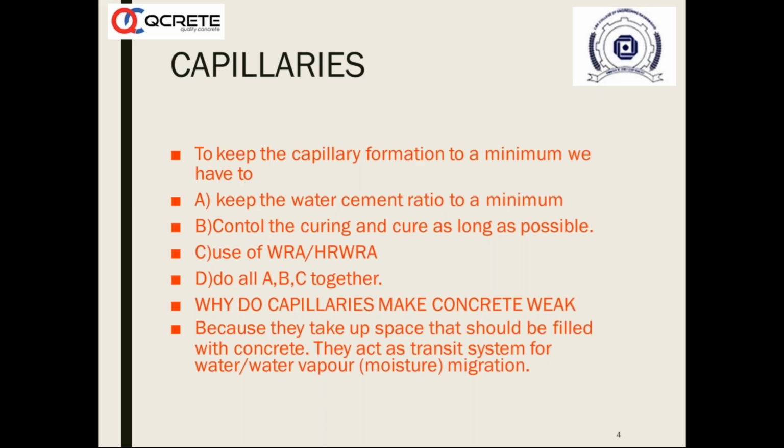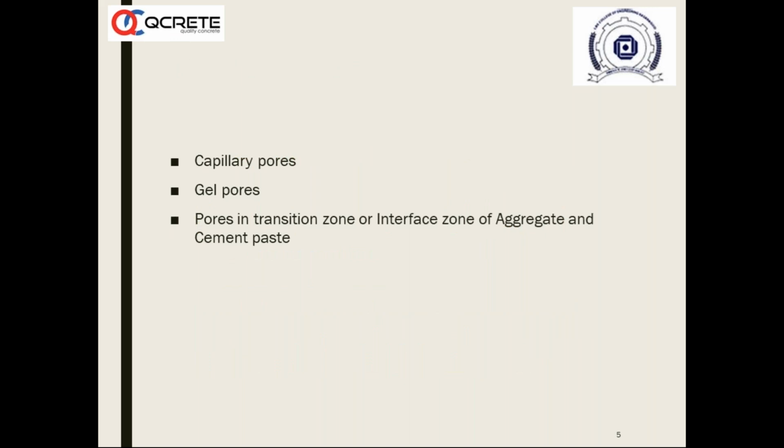You have a lighter material on one side, that is cotton. On the other side, you have a very heavy and dense material. So obviously the strength of such a dense material will be more. So if you have concrete with a lot of pores, you will have lesser strength. That is why we say that the strength of concrete is inversely proportional to water cement ratio.